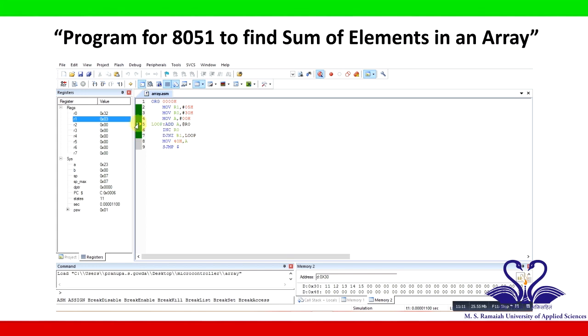Since it is not 0, it goes back again to the loop. Then ADD A, @R0. It was having the result of these two. Now 13 will be added with the accumulator value. So 23 plus 13 will be added and you get the result 36.